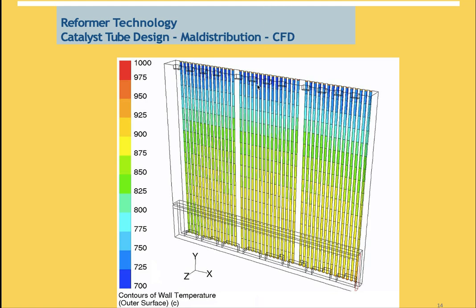What will you do if you remark hotspot or overheating along this tube? The root cause can be flame impingement, or poor distribution of the firing system inside the reformer, or the catalyst channeling itself, or coke laydown, or burner misalignment. Why can the coke laydown lead to hotspot?